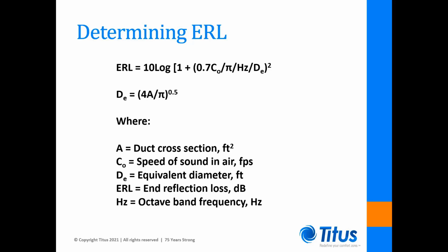The best explanation is that discharge sound paths involve ductwork and many different sources of attenuation that are difficult to fully account for. This complicates the estimation, but generally works in our favor to lower room sound levels.